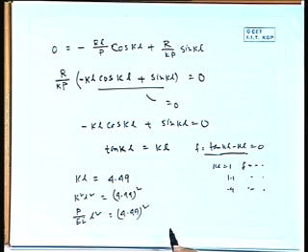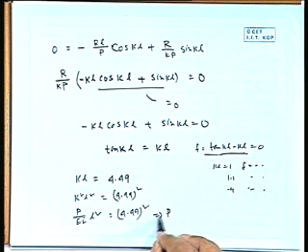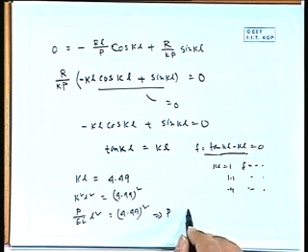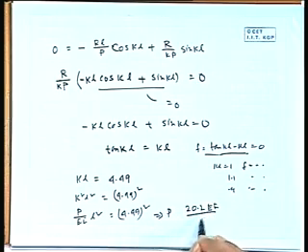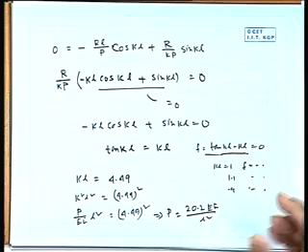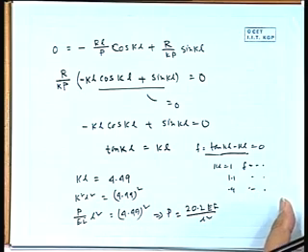Right. So 4.49 squared equal to 20.2. So P equal to 20.2 EI by L square. Roughly this value, you can take more significant digits.